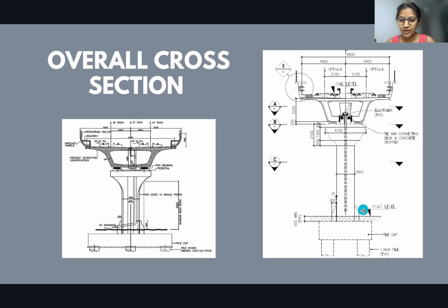And then we have something called the pier starter. Pier starter is where, I believe in the pier segment we have spoken about the extra reinforcements that were provided there. From there we have all of these piers. Now this pier construction also takes place stage-wise. There is one stage of concreting and reinforcement works, and then in the next stage the complete concreting of it will be done.